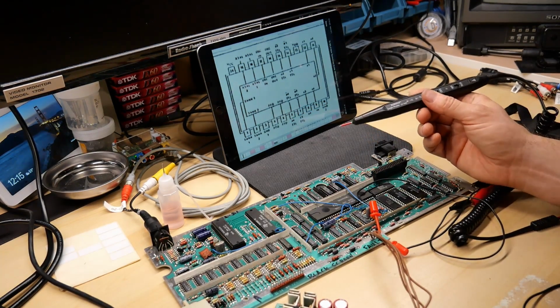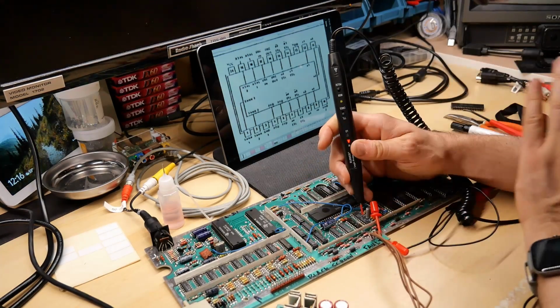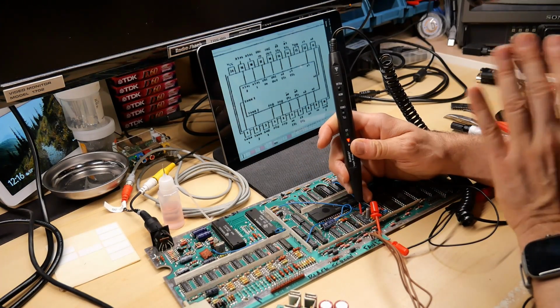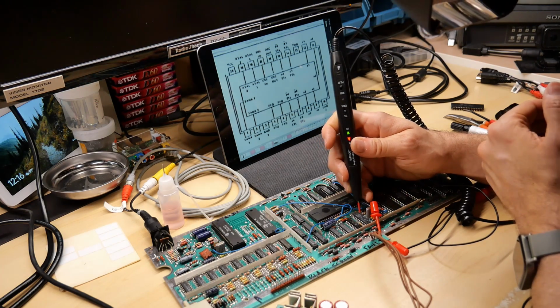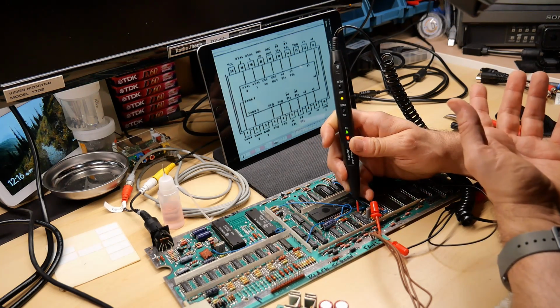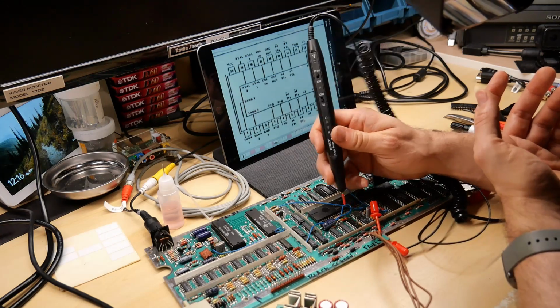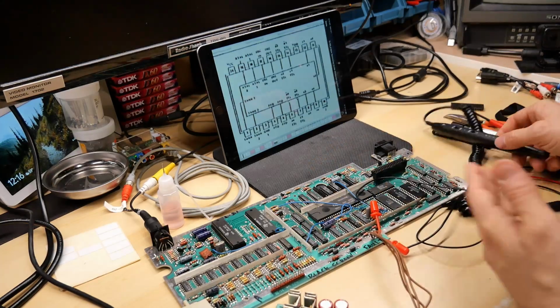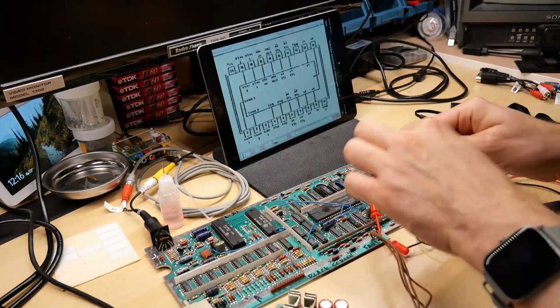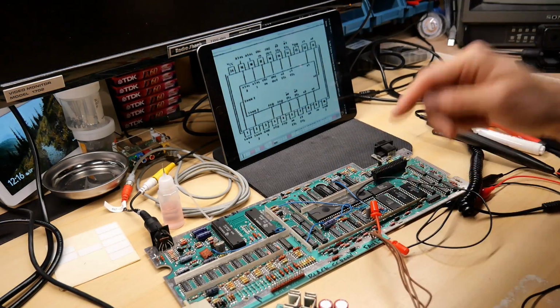So starting at pin 6. That's pin 6, it's pulsing, that sounds good. That's a TTL one as well, it's beeping, so that's good. That's one of the 12-volt clocks, so that sounds good. That one sounds faster, but I'll need to look at the oscilloscope to see if it's working correctly. And then this one. They're all beeping, so that sounds normal, but I'm going to need to check with the oscilloscope to see for sure.